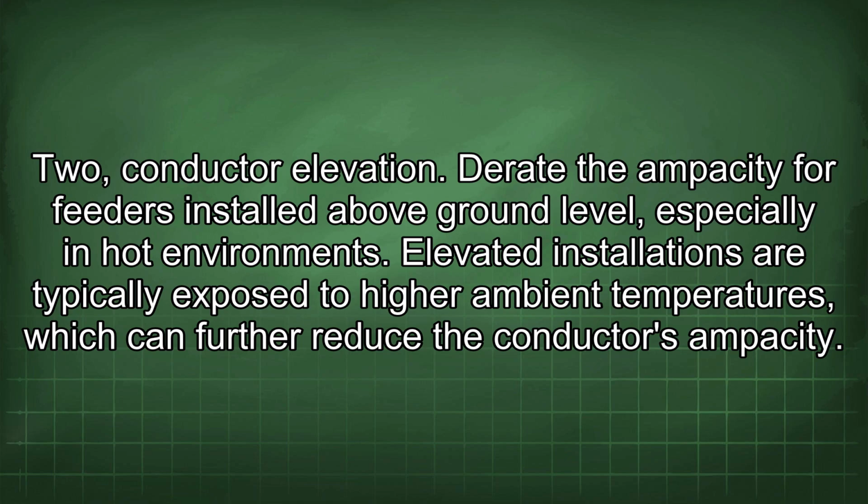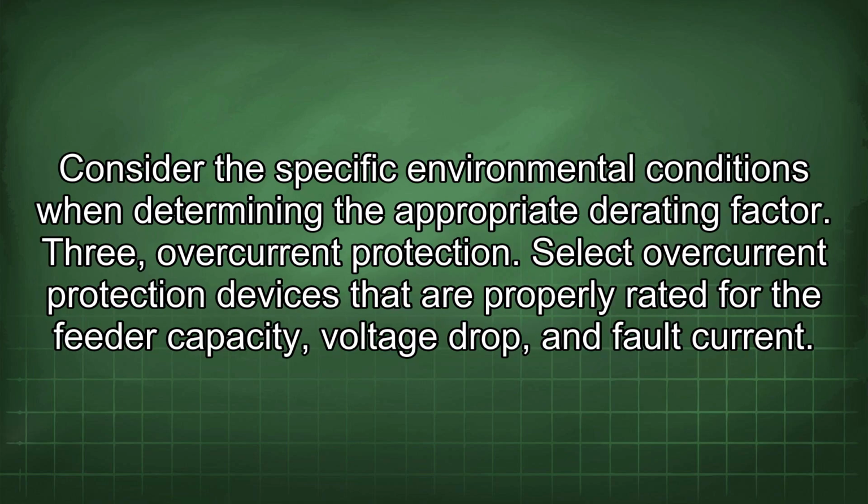2. Conductor elevation. Derate the ampacity for feeders installed above ground level, especially in hot environments. Elevated installations are typically exposed to higher ambient temperatures, which can further reduce the conductor's ampacity. Consider the specific environmental conditions when determining the appropriate derating factor.